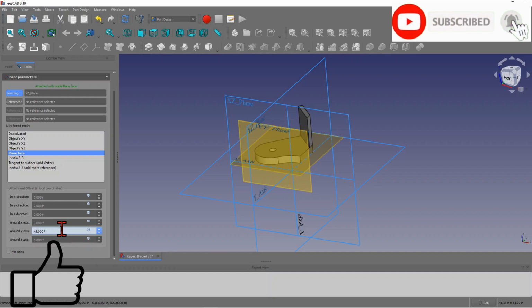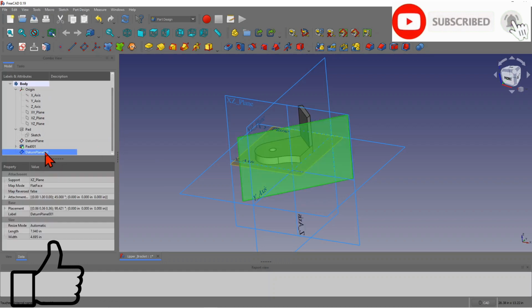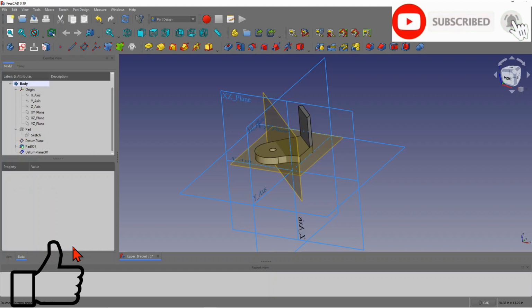Since I want to rotate it about the y-axis, let's see what happens. Yes, it rotated about the y-axis, but in the other direction than I want, so I need to go back and put a negative sign and enter. Now this plane is not exactly on this face, but it is over here. Now I can deactivate the origin.